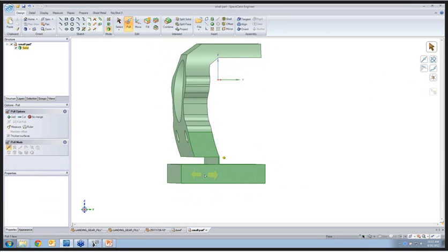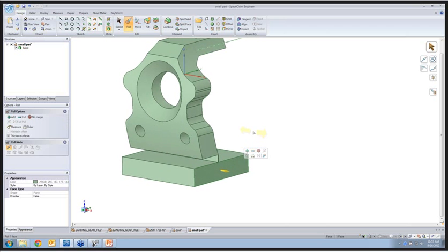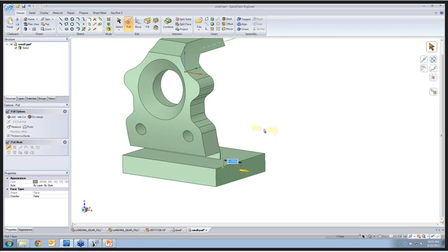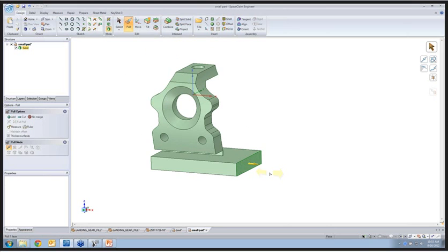The one on the left-hand side, maybe I'll eyeball and just say that base looks wide enough, okay? One more split face operation I want to do because I want to take that bottom right face and extend that out, okay? Maybe we'll call it a 1/2 inch. And by the way, sometimes I like to do dynamic changes and not put a dimension in, but you can always put precision into your changes that you make in SpaceClaim. You saw me put in a 1/2 inch offset to that face.